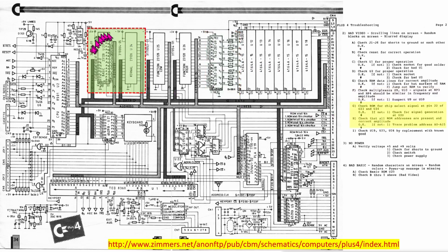And the ROM chips could of course be sources for error if they were pulling just one bit low. But as we saw, the computer is actually booting and running into both the built-in programs and other stuff. So I do think that at least the kernel ROM is okay, but the character set ROM could actually be a cause of this, even though it's a less likely candidate.